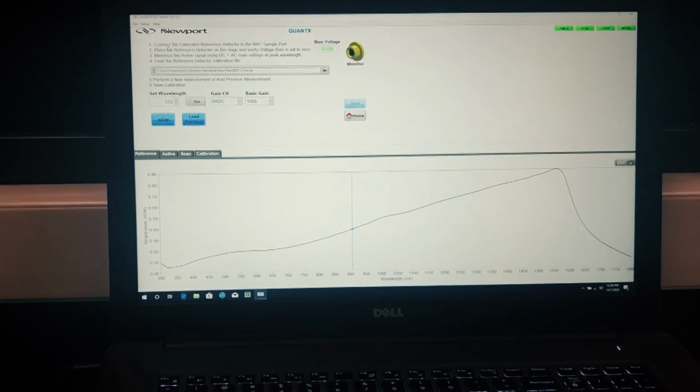The maximum value in this detector also shows a maximum responsivity very high, around 0.9, which is not typical for silicon. We can conclude that the reference detector is, most likely, a mixed detector, combining different types of materials with different responses, so that there is a sum in the responsivity when the response of the materials overlap.